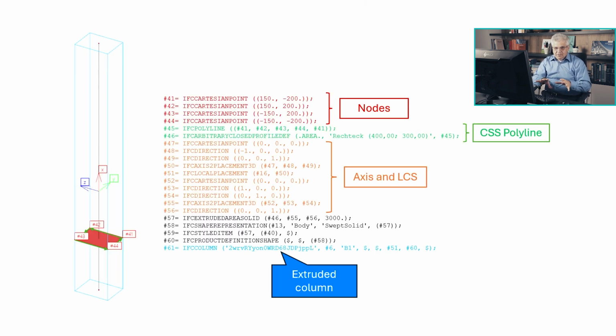So very often the decision, when it is exported from the CAD to IFC, whether you use the swept solid or boundary representation, you can decide in the software, in the way you create the object, or in some programs, for example Archicad, which uses an IFC translator where you can define it. So you simply have to use the right definition for the export, and then you get the correct object description.